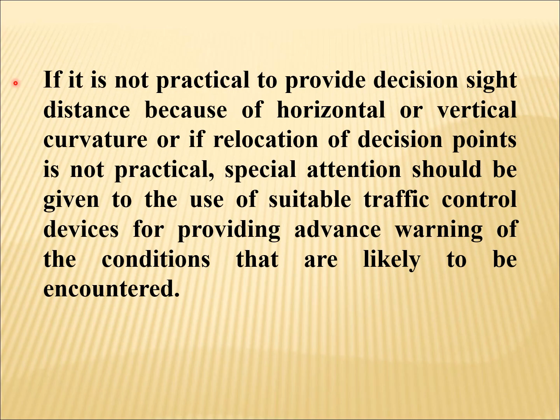If it is not practical to provide decision sight distance because of horizontal or vertical curvature, or if relocation of decision points is not practical, special attention should be given to the use of suitable traffic control devices for providing advance warning of the conditions that are likely to be encountered.